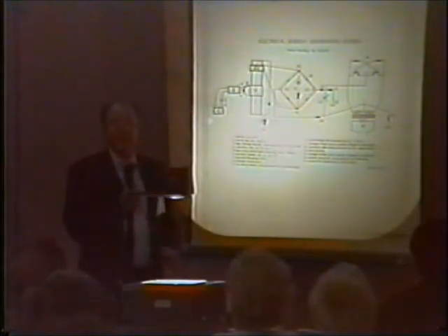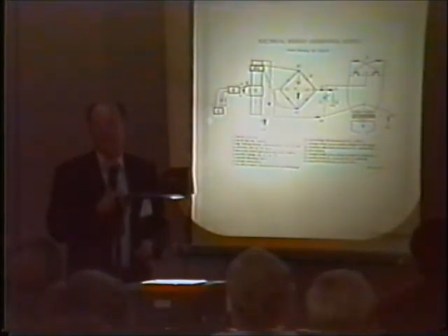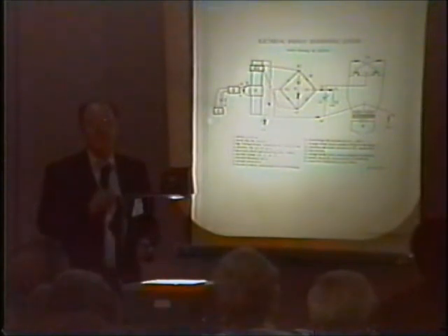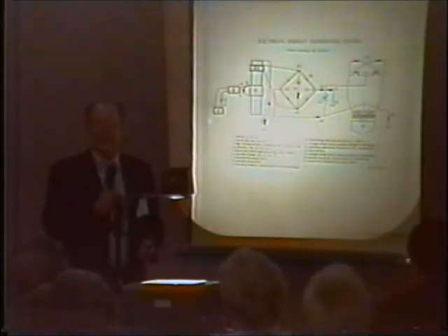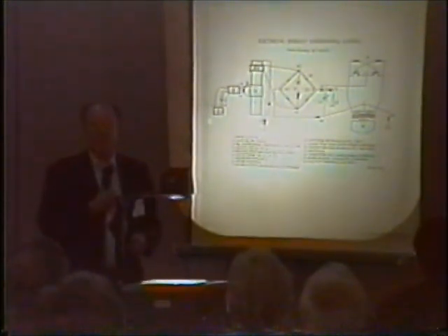The particular ones that I've used are 200 nanoseconds, which would be roughly about 4 or 5 megahertz, or can anyone correct me on that? 5 megahertz is 200 nanoseconds. It'd be about 5 megahertz. So that's high enough in your radio frequency so that if you multiply 5 million times your output there, you can see real quickly that if your output was even low, like a few volts and partial amps, all of a sudden you've got something that's much more potent than what it would seem to be.